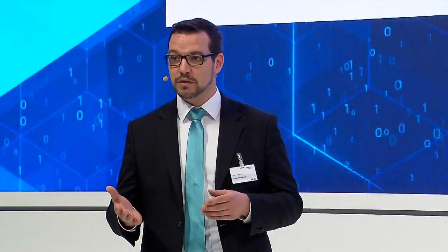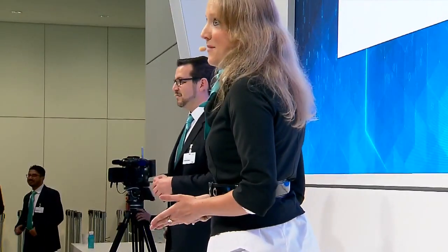We talked a lot, but now let's have a look how you can do it. The easiest way I would recommend is to use an S7-1500 and use the integrated connectivity with MindConnect function blocks. Engineer those function blocks in your TIA portal, download into the PLC. Basically, that's all, isn't it? Right. You just follow 3 very simple steps.